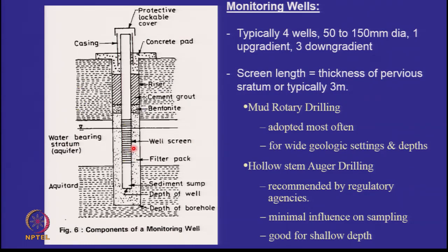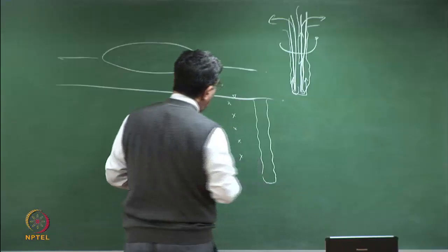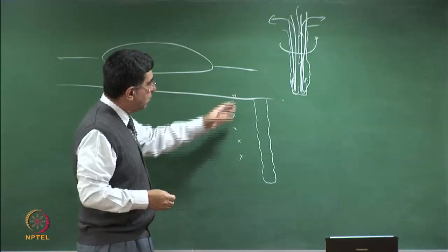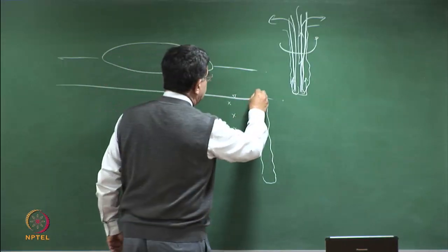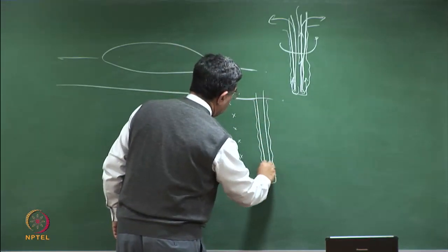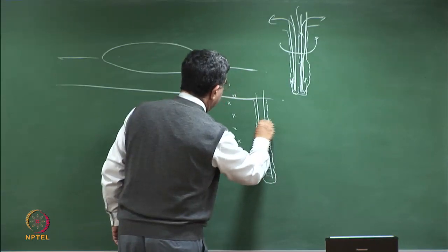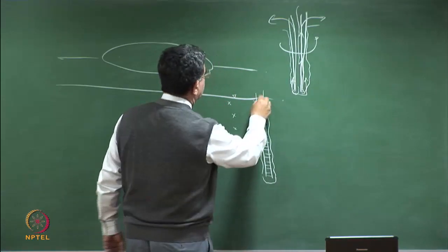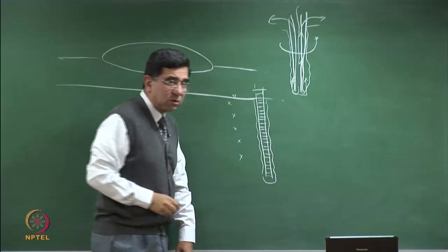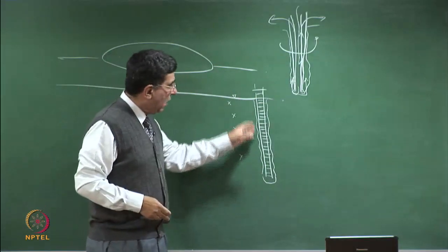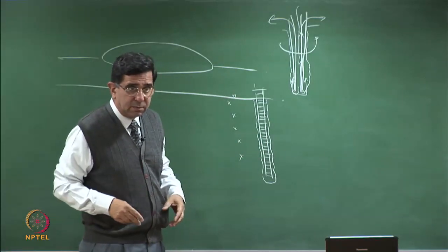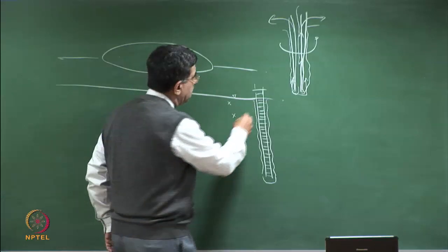So when I give you this problem, that please tell me the chloride concentrations in the groundwater at these 5 levels, you are very tempted to put a borehole. Suppose you put the screen, you say I will put the screen over this entire length, and then I will take the samples from this borehole. Please understand the gravel outside is making all these waters mix together. This has become a high drainage media.